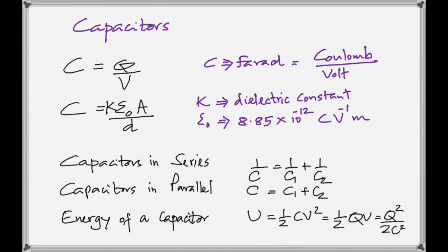What happens to the energy of a capacitor when the voltage on it is doubled? And then you'll have to look at, okay, which one am I going to use to answer? Obviously this is the one you're going to use because you know that C is a constant. So now you only need to look at, oh, the voltage is doubled and there's a square there, so the energy is going to be quadrupled. So you've got to look at which one to use and answer the questions.